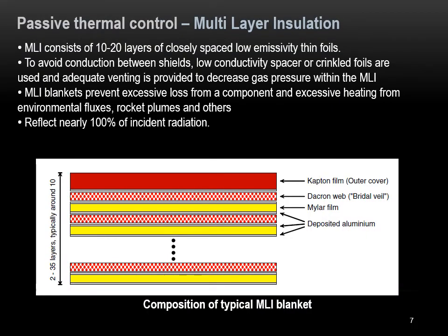The most famously used passive thermal control is multi-layer insulation, or MLI. MLI consists of alternating sheets of polymer material such as Mylar or Kapton and often looks like gold foil. We can apply MLI or simply Mylar or Kapton adhesive tape to a surface to vary the amount of heat absorbed by different areas and insulate the subsystem underneath.